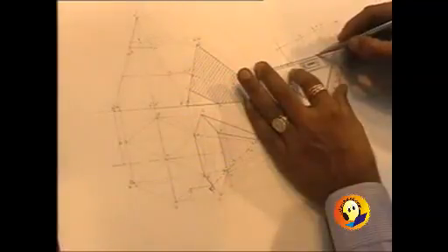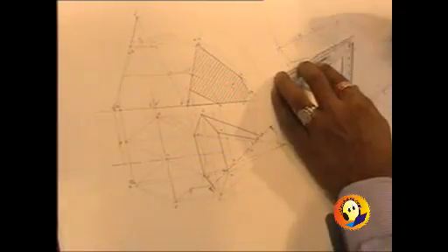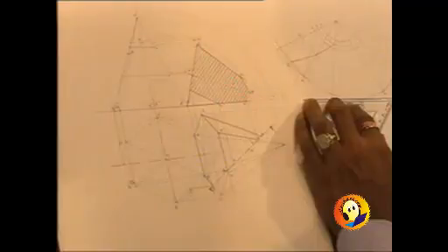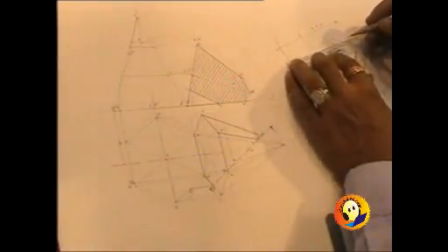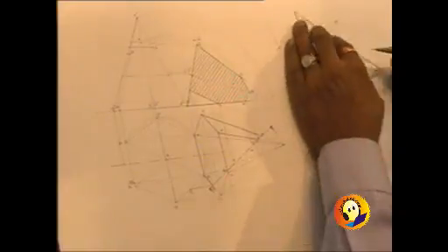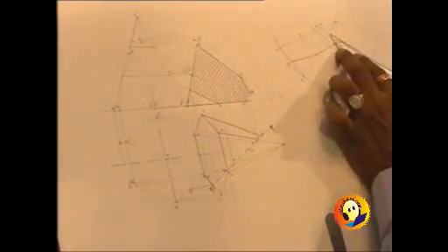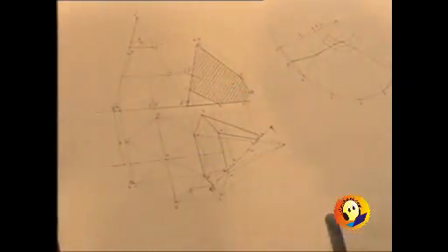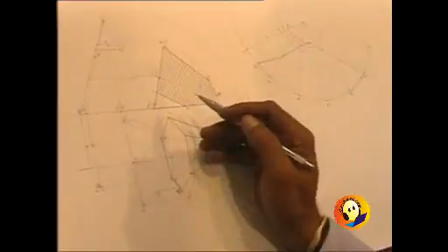So this is how the points will be marked, and now we are required to join them in sequence. So point 1 is connected to point number 3, then 3 is connected to 5, 3 is connected to 4, 4 is connected to 6, 6 is connected to point number 5, and then 5 is connected to point number 2. Observe, the sequence will remain the same as in the front view that we have obtained.